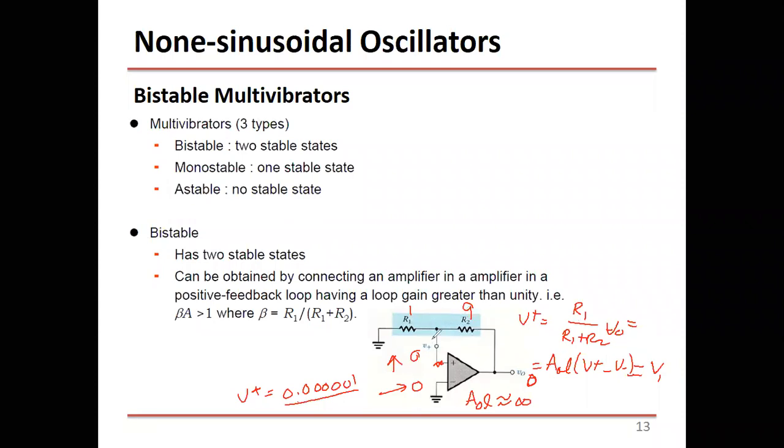So the voltage increases, maybe to 1 volt or something. And then you keep increasing, because this voltage will be amplified again to get V1 higher, and then fed back again to increase. So this will keep increasing the voltage higher and higher and higher.